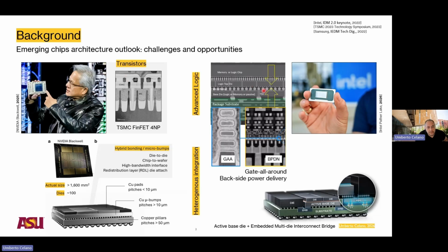On the right, the recently announced, this is not even 3 weeks old, A18 from Intel, Panther Lake. So this one is the first device, or first chip, which is coming equipped with the gate-all-around. So we're moving away from FinFET and changing architecture into gate-all-around and backside power delivery. Well, it's the first chip from Intel released with gate-all-around.